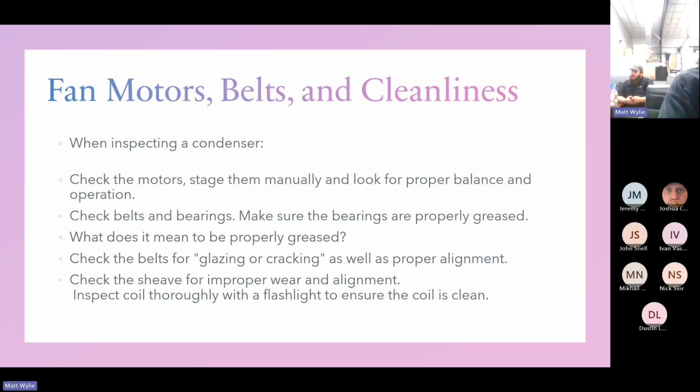They're starting to put them on Mitsubishi mini splits as well. I think he said when I went to the training that they were going to be an electronic expansion valve controlling flow to the compressor. So now you have 2 EEVs to deal with on one unit. So that's fantastic. I uploaded pictures in the chat too. That shows what we're talking about, just one version of what it looks like.